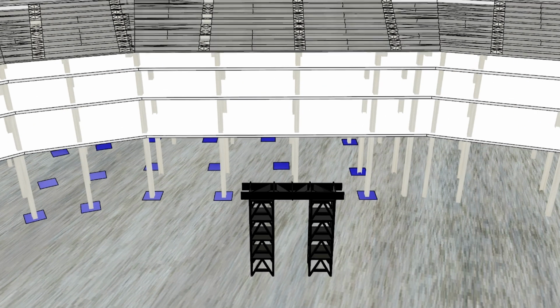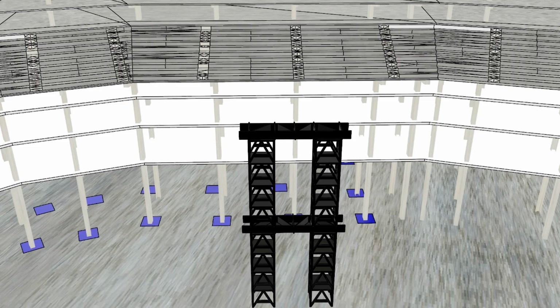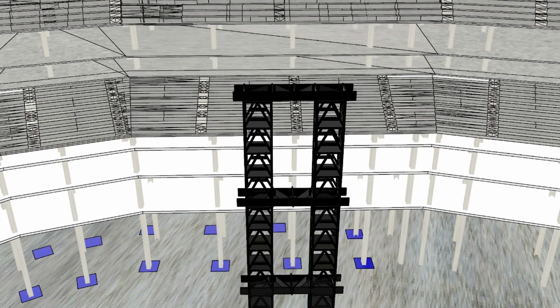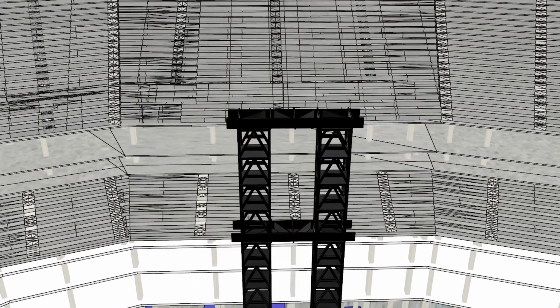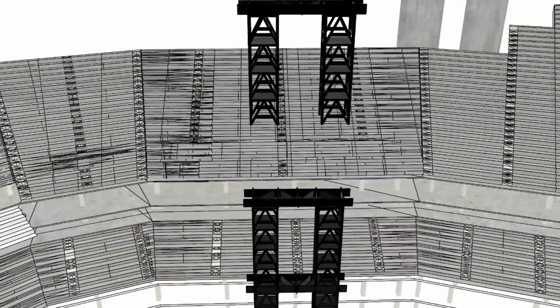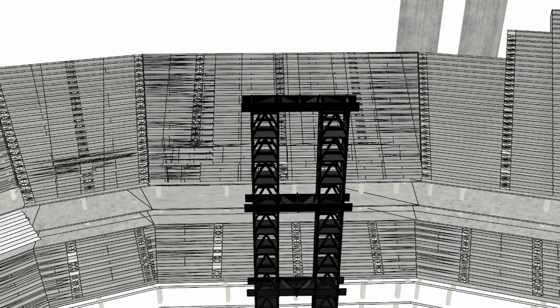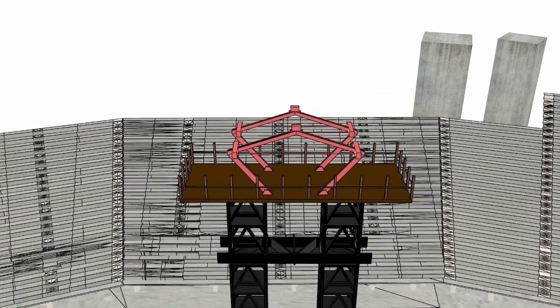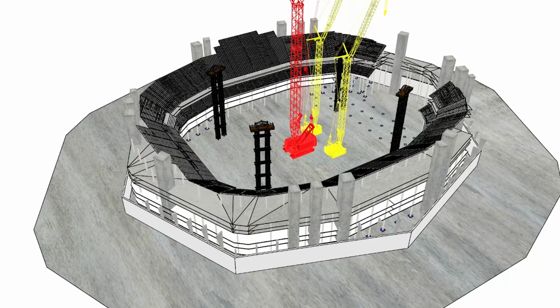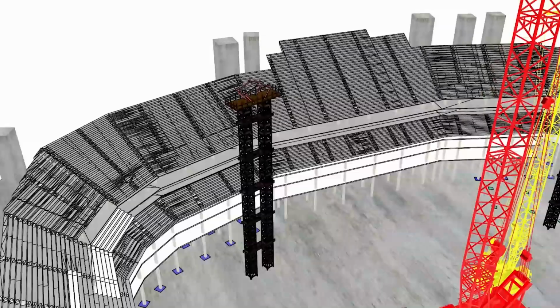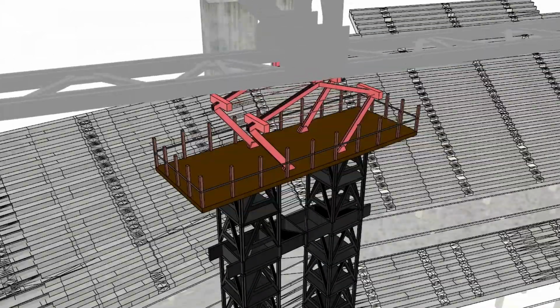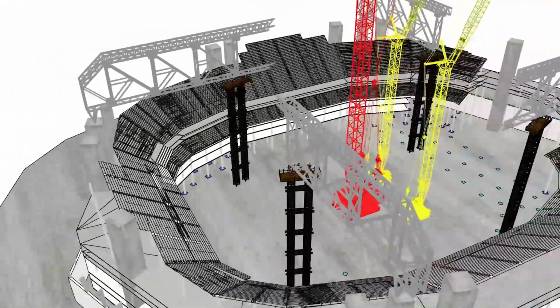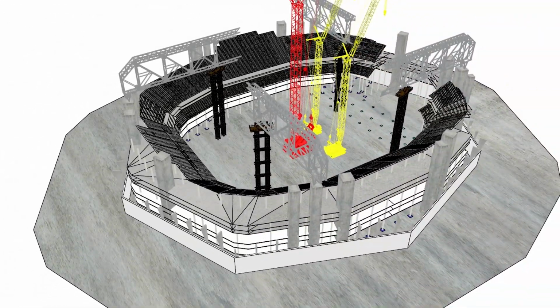Since the truss structures could not maintain structural stability on their own during the early stages of assembly, temporary support systems were essential. To resist this, 4 specially fabricated mega shore towers, each approximately 60 meters tall, were installed in advance. After the installation of the temporary support towers, primary trusses were first erected in a symmetrical sequence to establish initial structural stability.